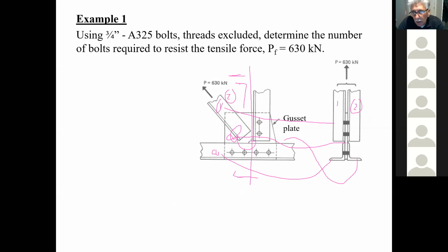So just to be absolutely sure, that section is going through the middle of the bolts of that vertical member, right? No. What I'm doing here is that, because I haven't done it yet, but here there would be some bolt holes. You understand? So what I'm doing is I'm already showing you that you're going to have some bolt holes across that. I apologize. I should have maybe drawn a couple of bolt holes, but this is just to show you that eventually you're going to have some bolt holes going across those two angles and the gusset plate.